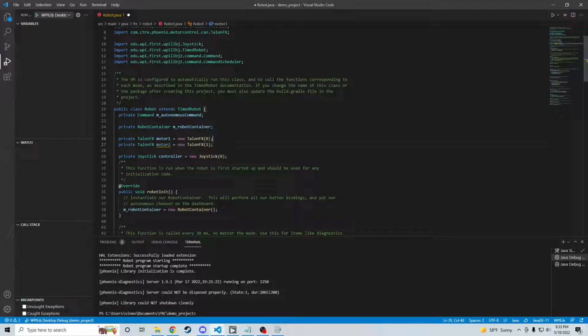So let's say this is the left primary motor, because I know on 1923's robot there's 3 motors on each side. You want to figure out the ID for the right primary motor. Any of the motors can be primary. Good practice is the frontmost motor, front lowermost or front uppermost, whatever you want to decide is your primary.